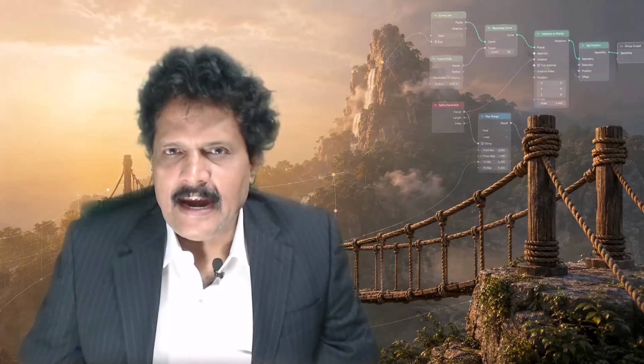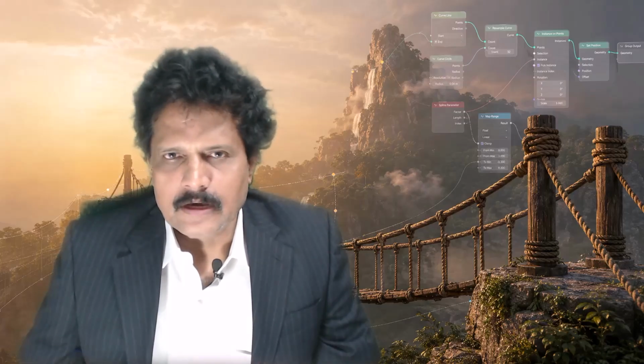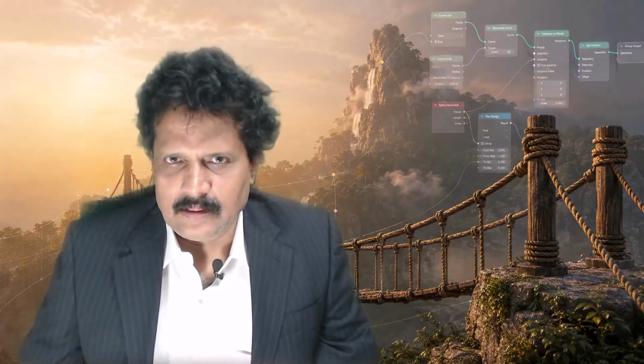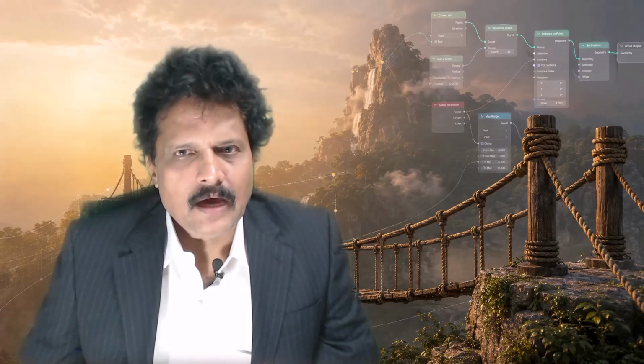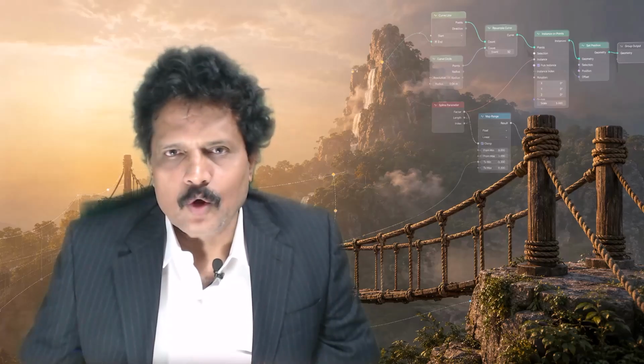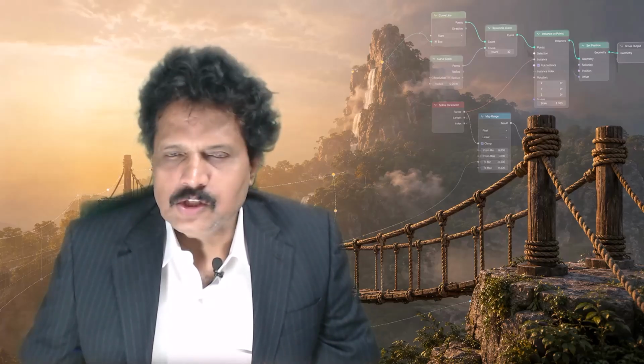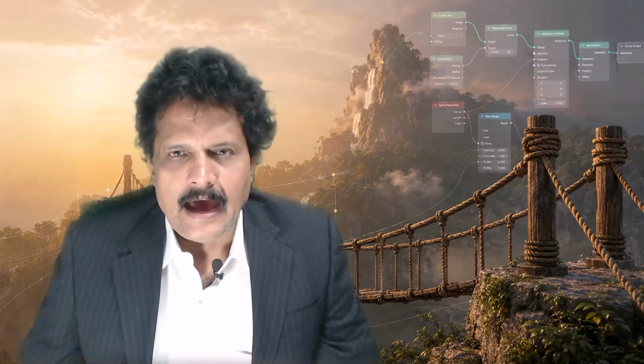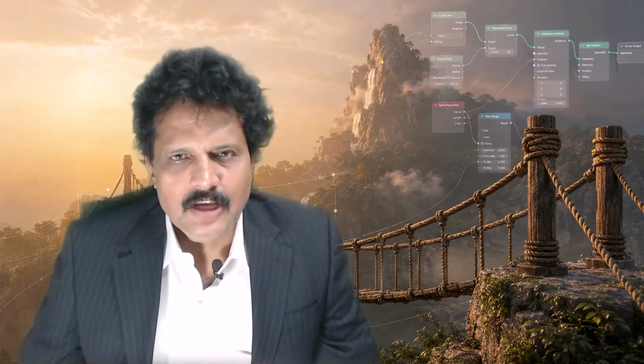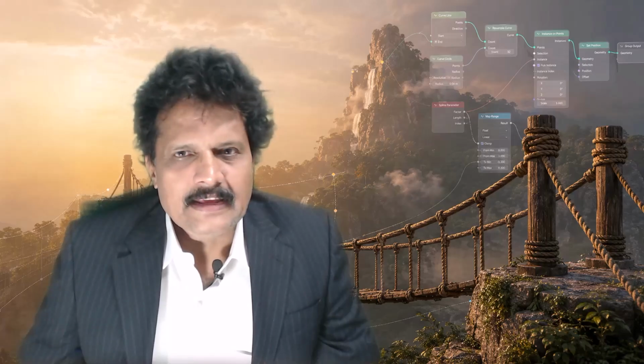In this session, we will begin transforming that framework into a visible 3D structure. First, we will add thickness to the rope using curve to mesh and curve circle. This will convert our simple curve lines into real rope-like geometry. We will also expose rope thickness as a modifier control so that the user can easily adjust the rope diameter without entering the node tree.